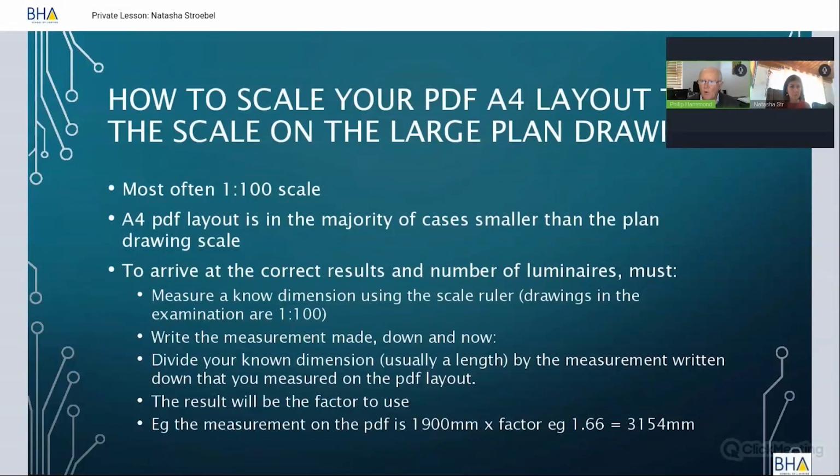And that will be an A4. But an A4 is way less than the big drawing that the architects prepared. So we've got to bring that A4 to the real size, because the scale that they use is 1 to 100 in most cases.